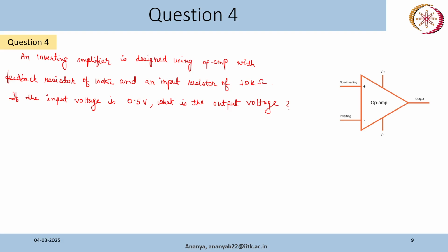Say your threshold level is 2 volt. If it is above 2 volt, it will turn the switch on or off. So if you directly use your inverting amplifier, which gives an inverted output, then the switch or the motor or everything will always be off, because it will be a negative value that is less than 2 volt, or whatever threshold voltage you are considering. That is why you should be careful about the configuration and the circuit that you are using after that.